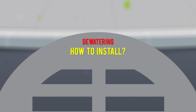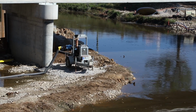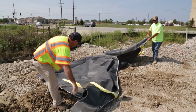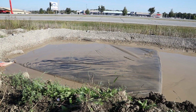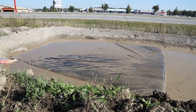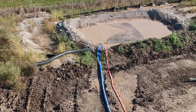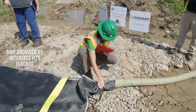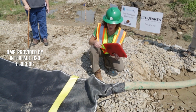How to install. The operator will furnish, install, operate, and maintain all drains, sumps, pumps, casings, well points, cofferdams, skimmers, and all other equipment required to properly dewater the site as specified. Volume calculations are performed to size the active or passive mechanisms for dewatering. Knowledge of site topography is used to install a dewatering system that will prevent erosion or sedimentation. A water or soil test is conducted to determine the appropriate flocculant agent necessary to clarify turbid water.